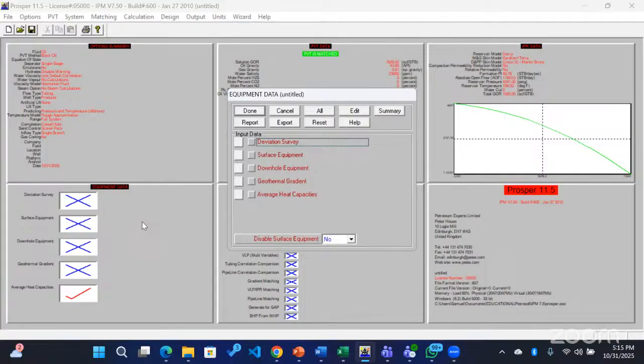Then delivering the fluid or our oil into the wellbore is not the end of our production. So we have to look at another concept, which is VLP, vertical lift performance, which is deliverability of that fluid beneath that wellbore into the surface. So that's a simple term. I don't want to speak big grammar.